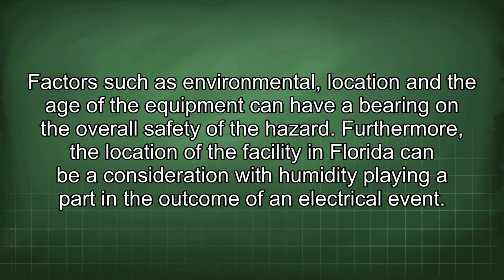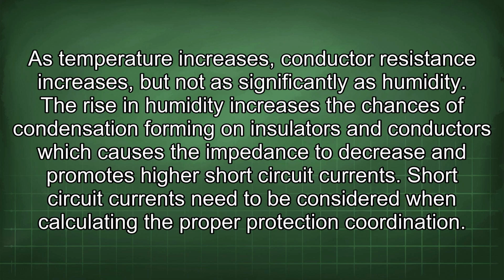Furthermore, the location of the facility in Florida can be a consideration, with humidity playing a part in the outcome of an electrical event. As temperature increases, conductor resistance increases, but not as significantly as humidity. The rise in humidity increases the chances of condensation forming on insulators and conductors, which causes the impedance to decrease and promotes higher short-circuit currents. Short-circuit currents need to be considered when calculating the proper protection coordination.